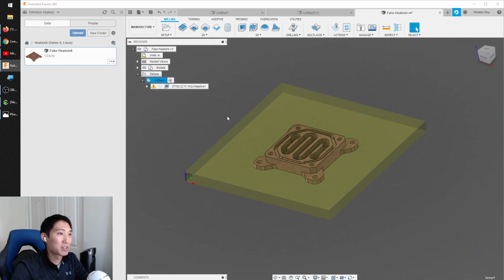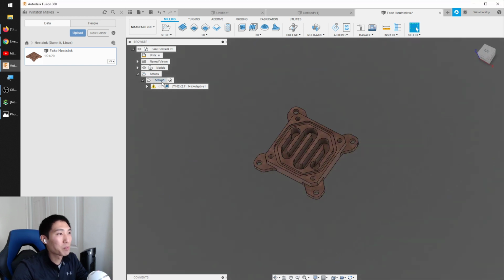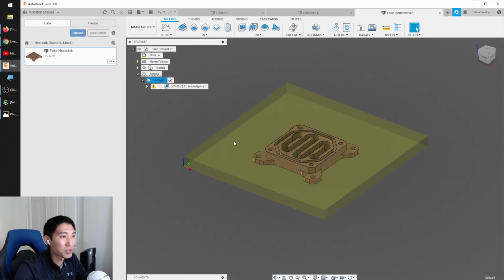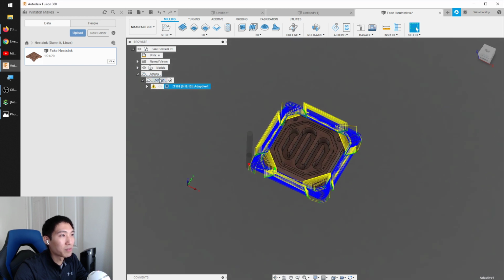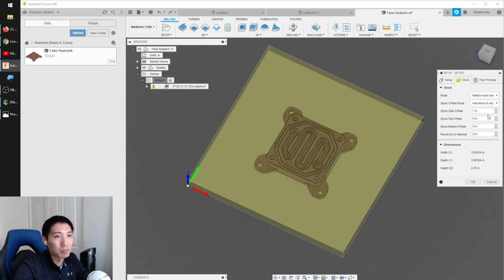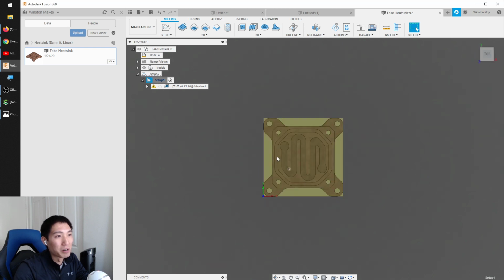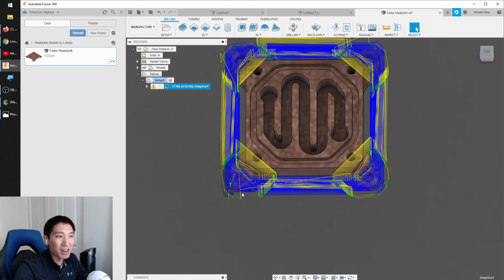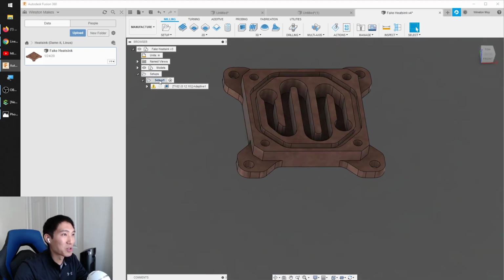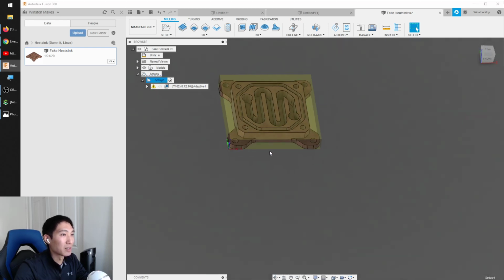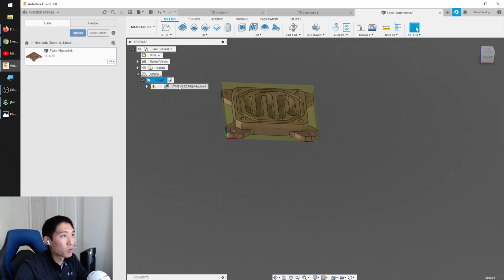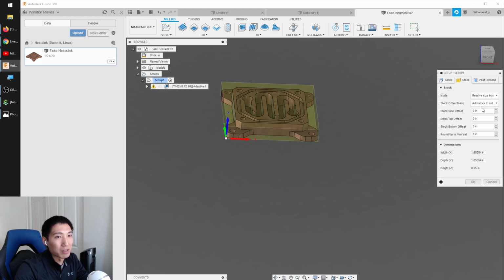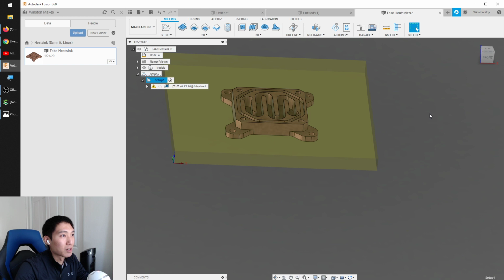Now, the reason you would want to make sure you have a little extra stock modeled in here is that if you recall the previous toolpath, if you said your stock is this big, but it's really a little further out, it's going to start the adaptive toolpath in the middle of the stock, and you're just going to break a cutter. So always make sure that either your stock is just a fraction of a millimeter bigger than it actually is, and you set your zero correctly, or it's okay to have a little more stock. You just need to constrain where the toolpath works.